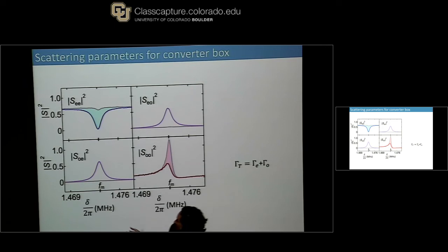And the peak efficiency is at the mechanical resonant response. And if we go a little bit off, then it's not as good. And what we can also see, I focus on the blue one there for the moment, is that when we originally stick a signal in but don't have this impedance matching condition that's going to suck energy out the other port, we can see a lot of light is reflected from the electrical port, and that's what the gray curve is.